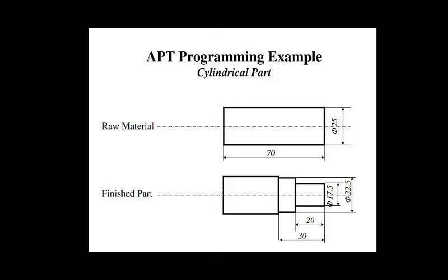In Part 2 we have seen the advantages of NC system, disadvantages of NC system, CNC programming basics, CNC programming, also the important things while doing the CNC programming, and also the meaning of the various key letters used during programming. For example, O for program number, T for tool designation, S for spindle speed designation, M for miscellaneous function. Along with that we have seen the G codes.